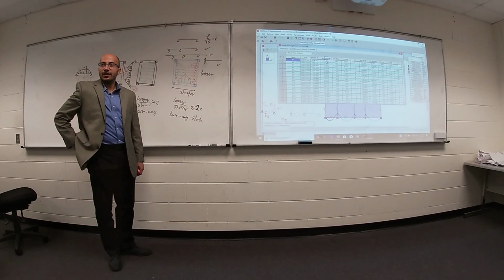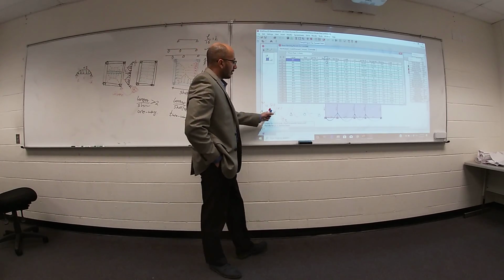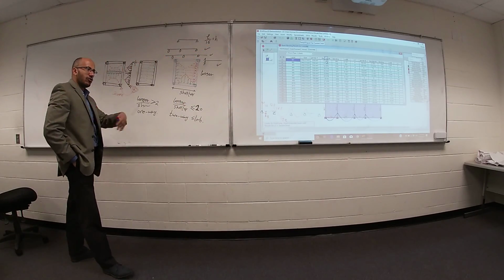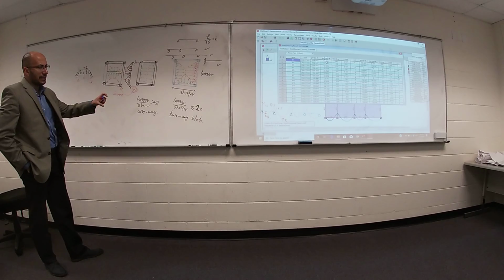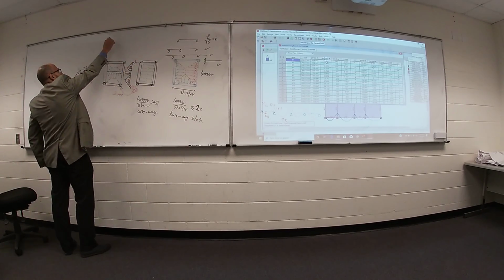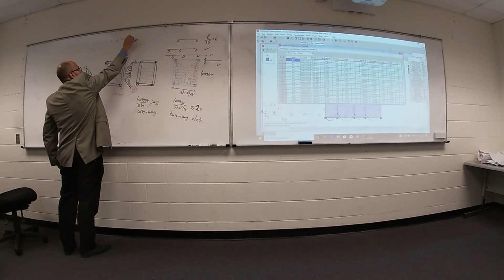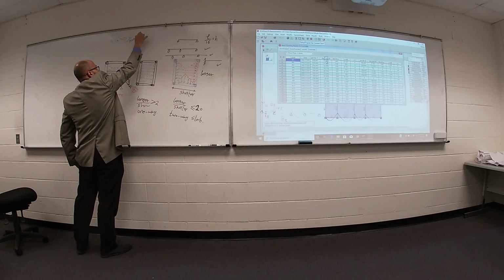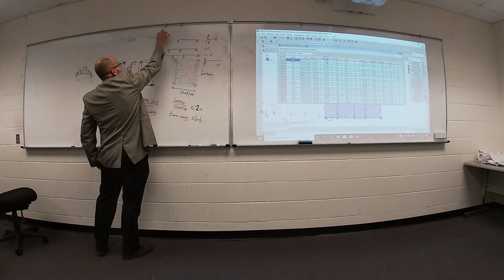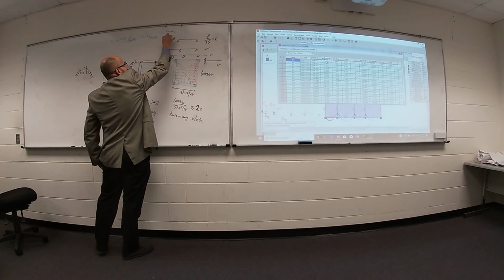What's next? Go ahead and design your beam. Or wait until you get all the values and use the biggest value. You can use the biggest value and make your reinforcement the same for the whole beam. So if you remember, if you have M ultimate, I can tell you what is the rho required, and I can tell you what is the area of steel required. And I can check if this area of steel required is within the limit, area steel minimum and area steel maximum.